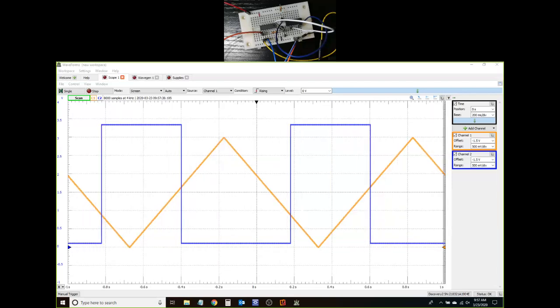For a Schmitt trigger, will the V3 positive reference change if the input voltage changes from Vin greater than V3? V3 will not change. So we are trying to compare the input to V3. V3 is based off of the resistors R4 and R5. Let me bring that up.